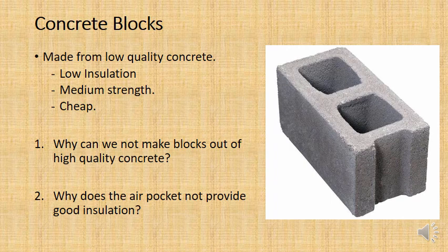Well, the reason is because this air is exposed to the atmosphere. The void ratio is so high that the voids are not individual air bubbles inside the concrete, but rather they are veins or channels that run through the concrete. So basically, the temperature that is outside will be the temperature that is inside, or potentially even worse.